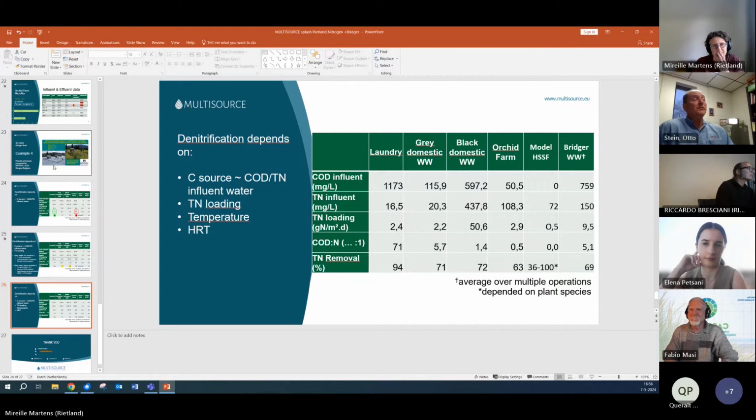Well, we've been trying to characterize this a lot more. I think the media size is going to determine what the specific retention volume of that media is going to be. So we have been looking at both the new pilot system that we've built at our Bozeman wastewater treatment plant and also in the lab, trying to characterize the dose volumes relative to the specific retention of that particular media.